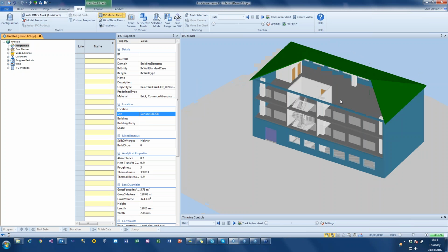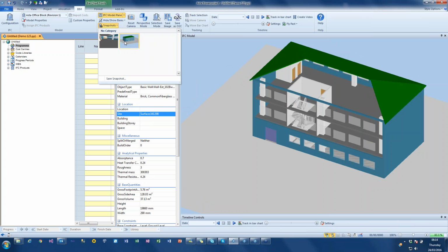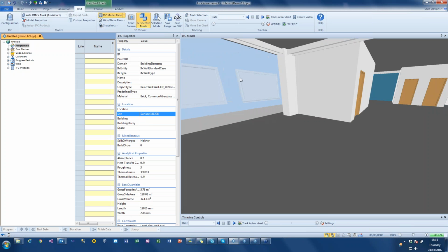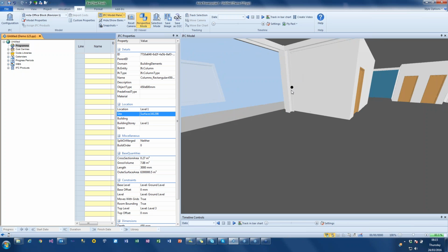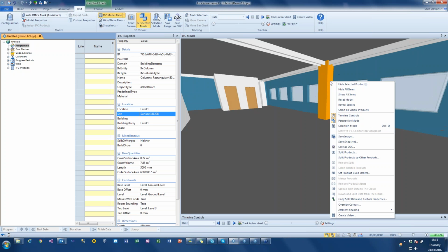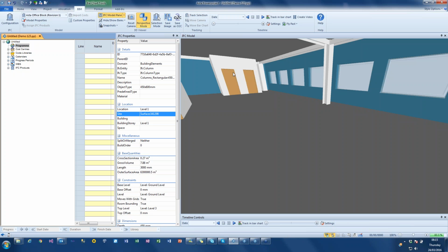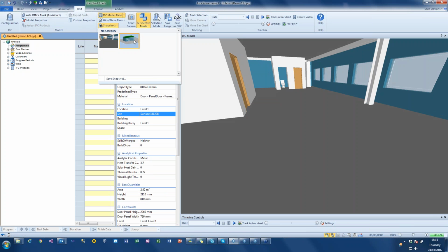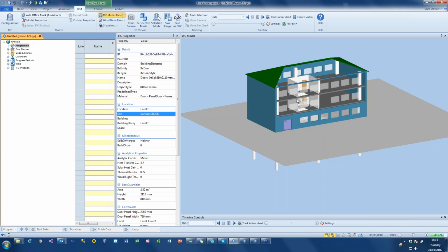And if I do that, then at any point I can still go back to my snapshot there, and you can see I've looked there, and even in through this view I can hide items, look at those beams, hide that, so I can look at those inside, I can hide those, so I can interrogate it as I look through, and then just pop back to my other snapshot to see from that point there. So very quickly move back and forth between those. I can also, if I go to show all items, turn it back on and see those.